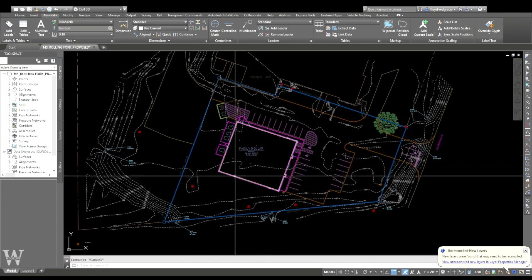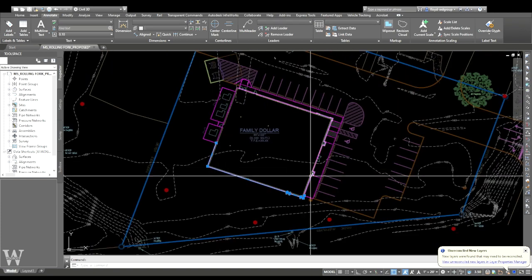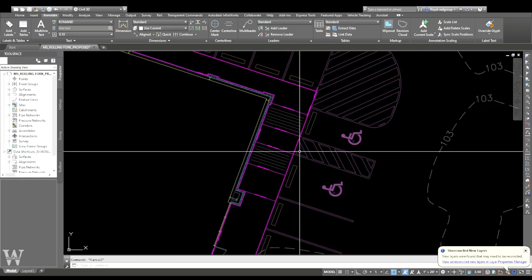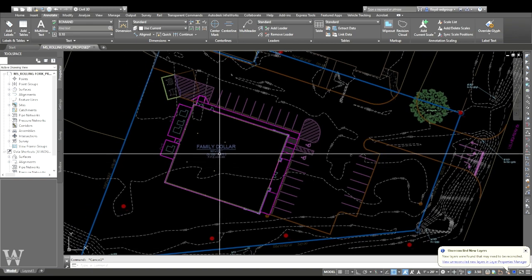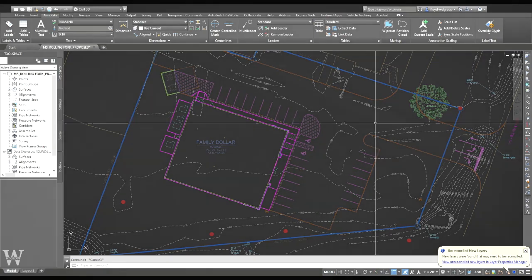That way, then I come back and if I do my surface and I forgot to do them, I'll come back and fix them and change them, and then they'll become feature lines, and they'll go to that feature line layer. So, all right. So that's end of part 1. We'll pick up with the next phase of grading in part 2.